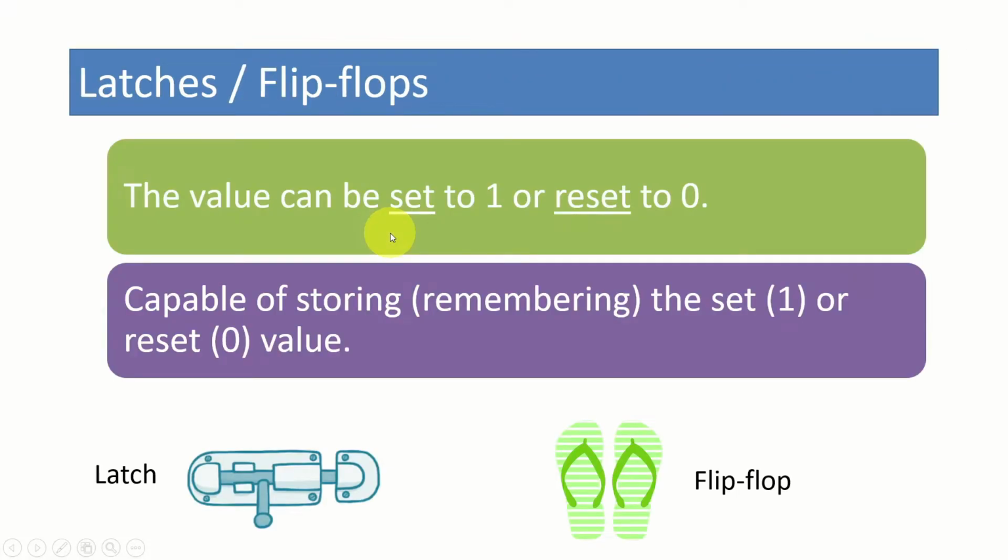Let's look at what is meant by latch or flip-flop because we are interested in the SR latch in this particular session. A latch or flip-flop is a sequential logic circuit component which is capable of setting to a value or setting to 1 and also resetting to 0, and also it is capable of remembering or storing that value, the 1 value or the 0 value.